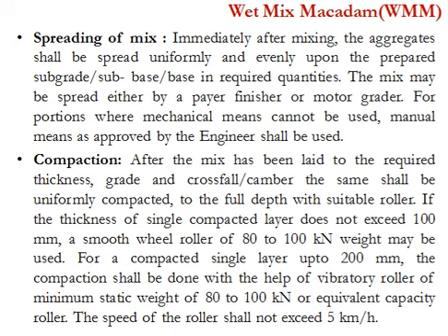So spreading of the mix is the fourth stage or the fourth process. Here, immediately after mixing, the aggregates are brought to the site and spread uniformly and evenly upon the approved subbase layer. The material should neither be dumped in heaps nor be allowed to fall over a partly completed stretch.